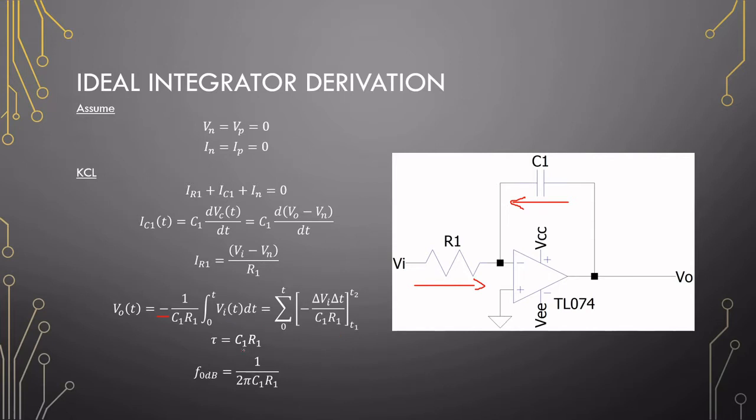Now this time constant, or this 0, we want to place as close to 0 frequency on the Bode plot as possible, so that we have a 20 decibel per decade decline across the board.